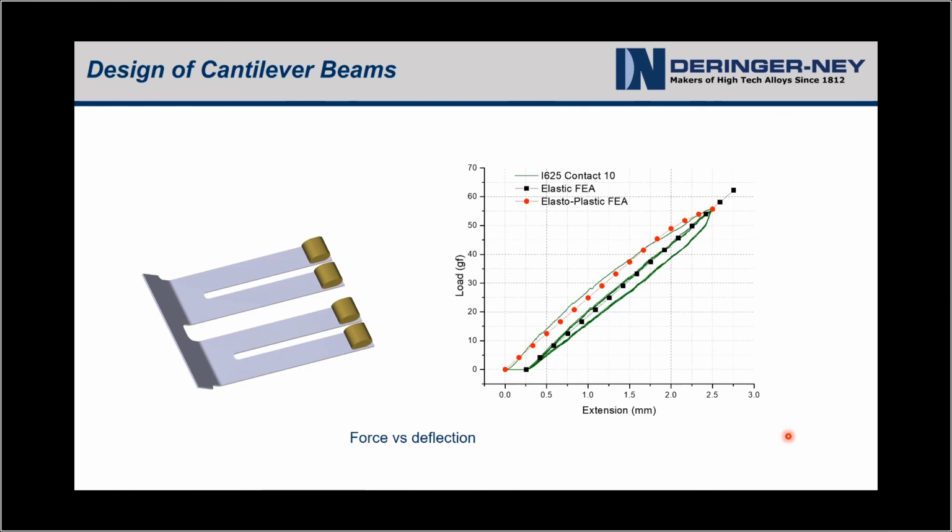Here you see that the elastoplastic did an all right job anticipating the behavior of the part in the first cycle. And then if we shift over the elastic curve, after the contact's yielded, it will be elastic between 0 deflection and the yield point.